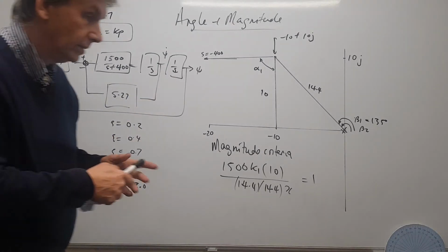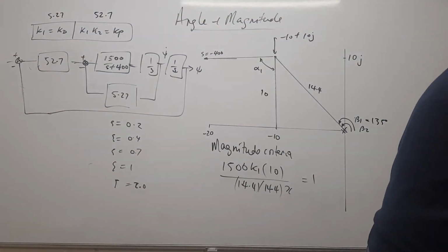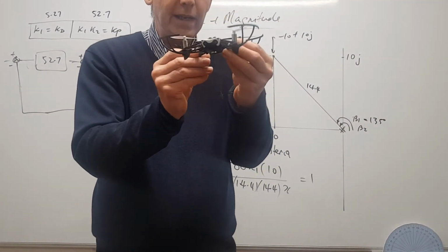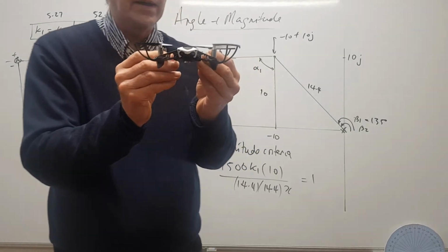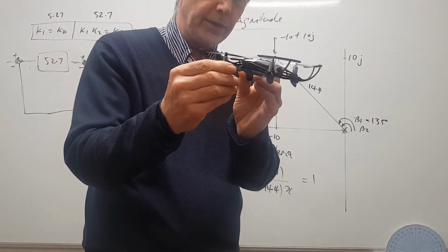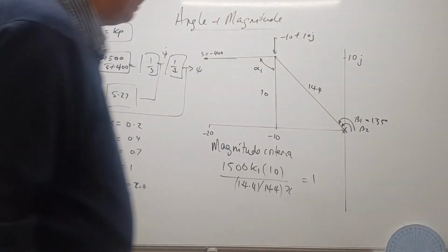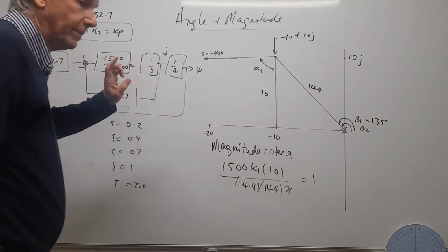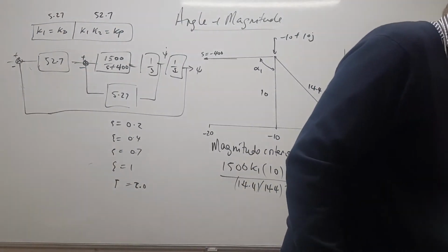And what I'm hoping to do, we'll see how it goes, is get the drone to come up, point towards you, and then do a little 1 radian turn. So 1 radian is about 57 degrees, so it's going to be sitting looking at you, and it's going to turn by 57 degrees, and we can see how well it does that task. So this is the design now of our yaw damper for the drone.